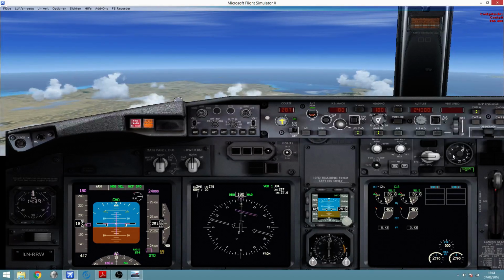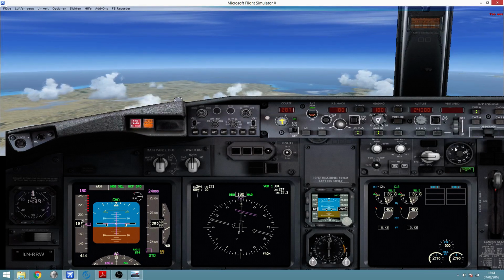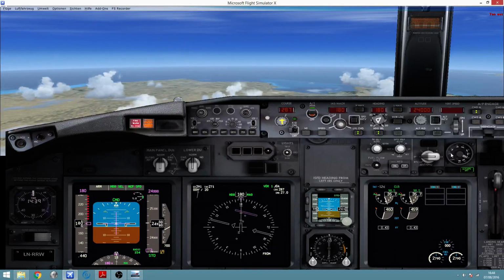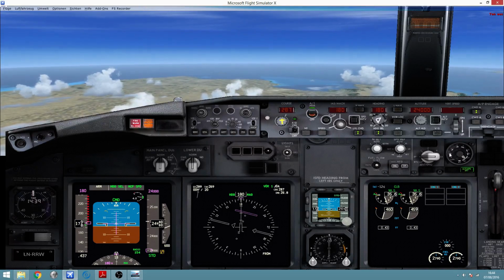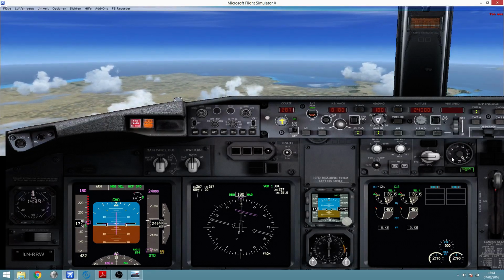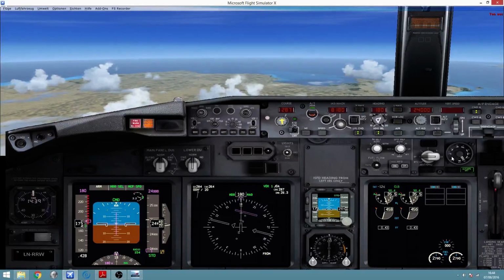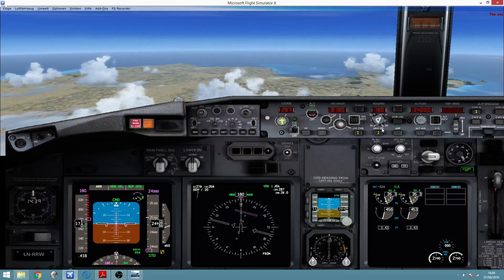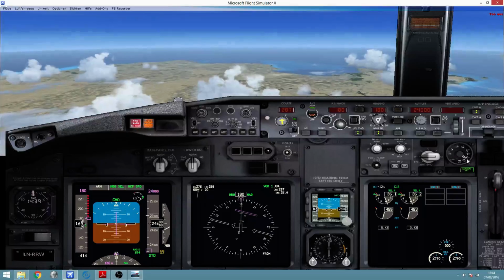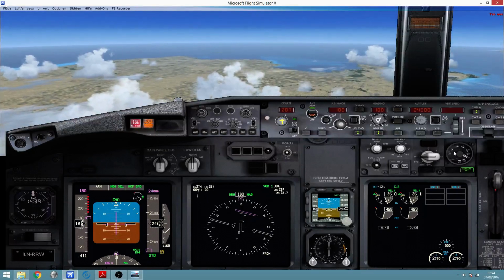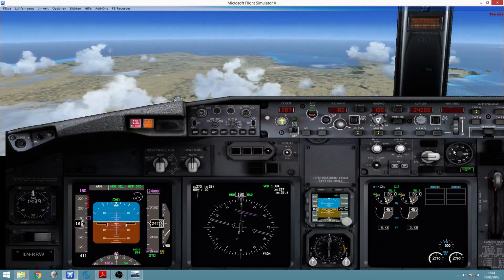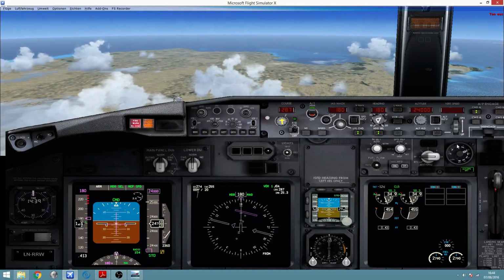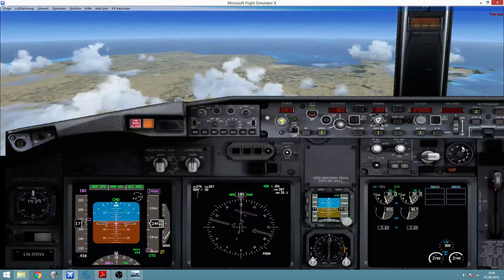here on the cockpit. This is the indicator showing you what is the extension of your flaps. So flaps of 40 degrees would mean full flaps. Flaps of 0 degrees would mean flaps totally up, and that's something we achieve pressing F5, as I just told you. All right, so I just pressed F5 to retract the flaps, and they are now being retracted. Each of these numbers indicates the degrees that the flaps are extended.